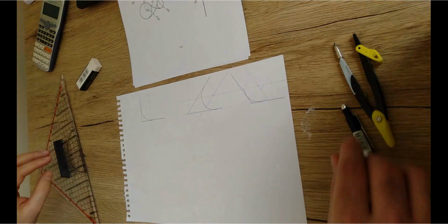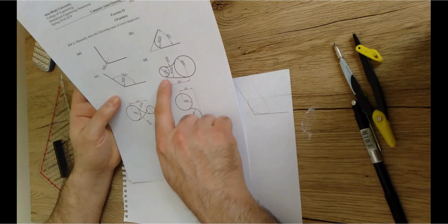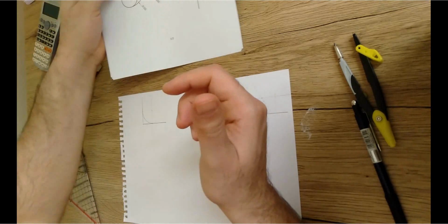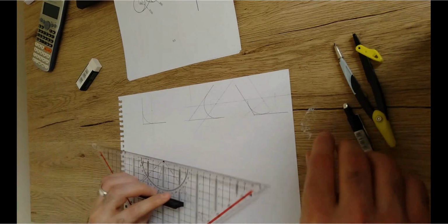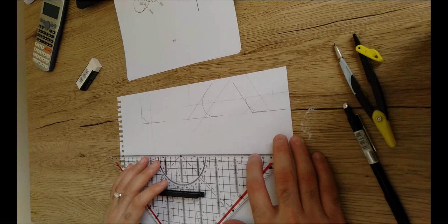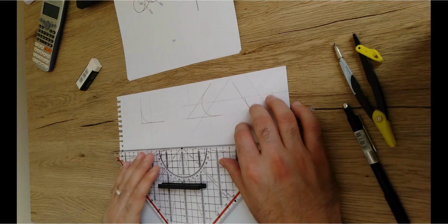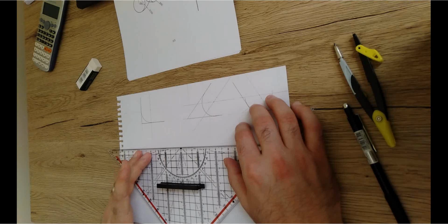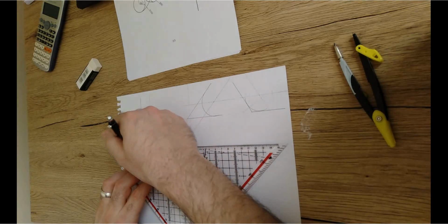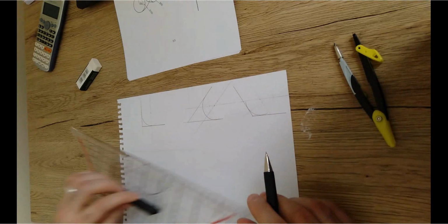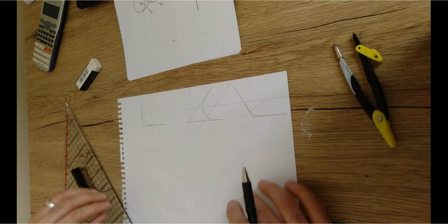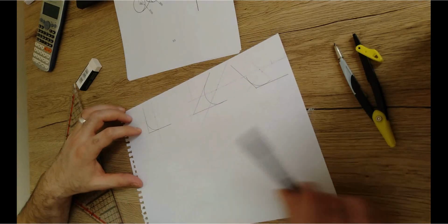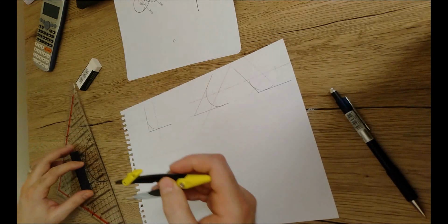The first circle we're gonna pick, it is with a radius of 20 because the diameter is 40, and we're gonna pick any point to be its center point. So I'm just gonna pick here. Let us draw a second row here. Okay, this one is enough. And I'm gonna draw this very long horizontal line to be like the second row, and over this point I'm gonna choose this is like the center point of the first circle, and it has a radius of 20.